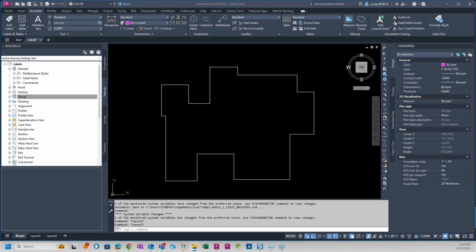Incidentally, somebody came up with a bright idea a while back. It was a great idea, but to use drainage areas as parcels. Well, that's great. It works fine and all, but when you take your pipes and your drawing into storm and sanitary sewer analysis and backdrop it in there, you can't see those drainage areas, so it doesn't do you any good as far as visually goes inside SSA. But anyway, line work definitely goes over there.